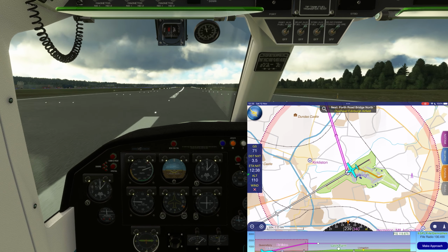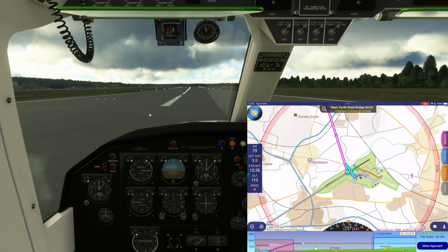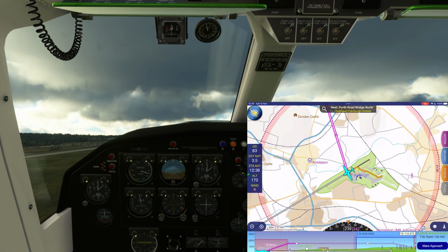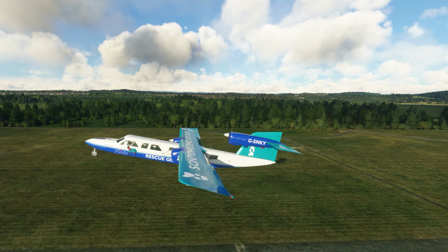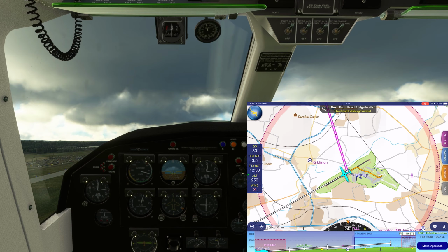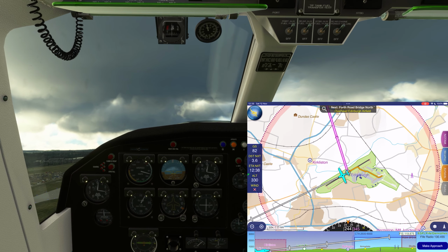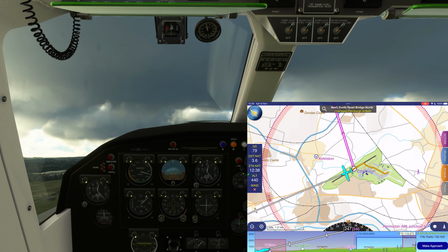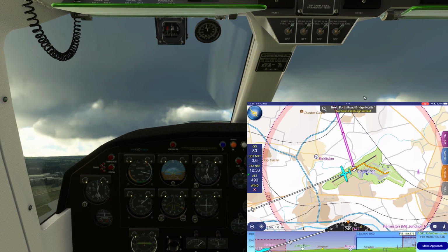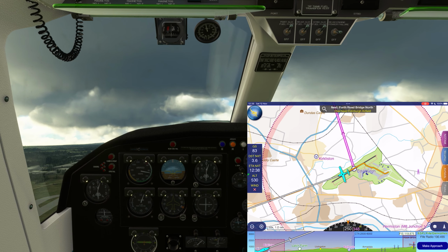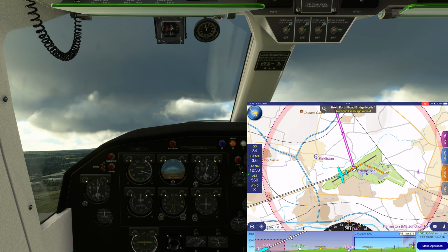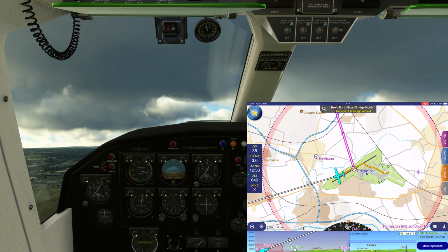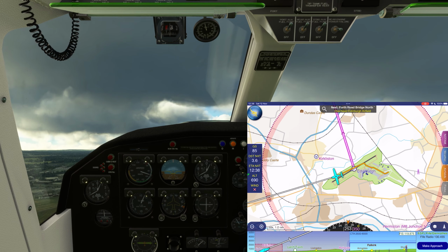Looking for 80 knots, holding straight. There's 80 knots and rotate. Climb between about 90 and 100. Okay, 200 feet above, flaps can come up. Rear engine power failure switch light is off, and we'll get power back to 25 inches and 2,500 RPM.